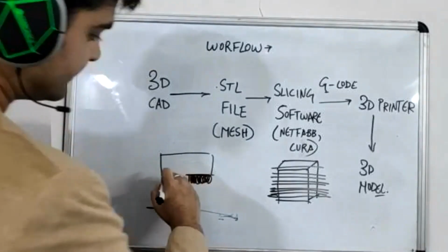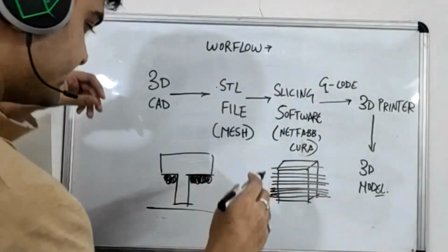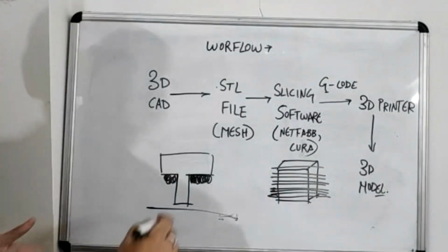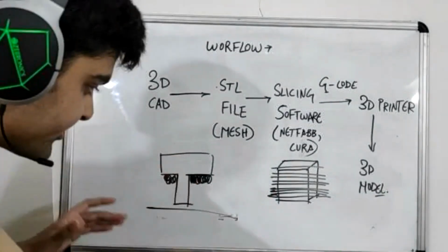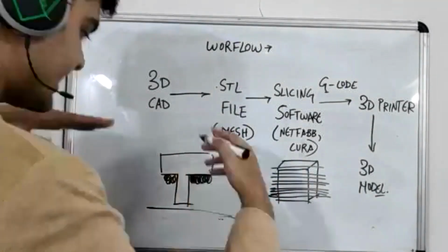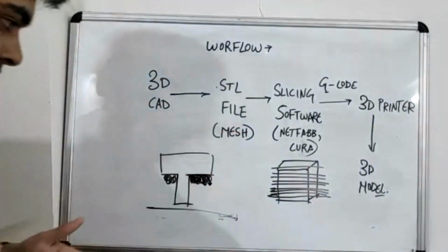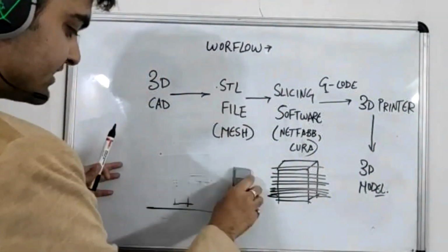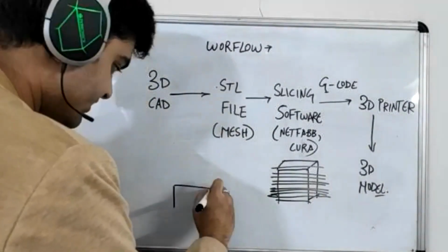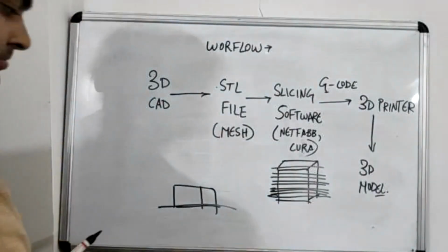This happens because when the filament in the 3D printer exits the nozzle, it's really, really hot, say 200 degrees Celsius, which means it has a tendency to flow. And when you don't really give it a lot of support, it'll have a tendency to droop down and ruin your entire design. One way to fix this is to lay the T block on its side like this. This gets rid of the problem, or you could use supports.